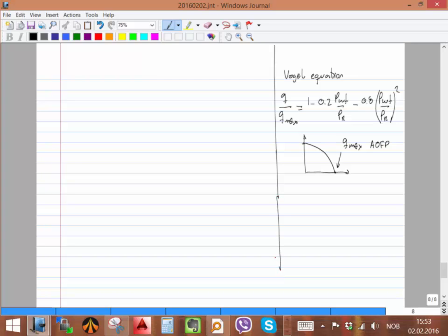oil wells. And you also have the gas equation, the back pressure equation. And that equation looks like this, QG, where N is all the time a value. N describes how the flow is in the porous media. If it's laminar, if it's turbulent, it tells you information about the regime of the flow inside the porous media, and it's all the time a value between 0 and 1. So you see here the problem. To use that equation,